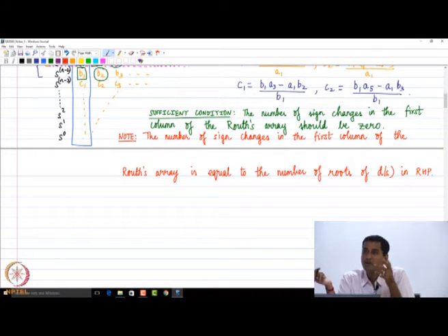How are they going to be reflected in this Routh array? Till now I only talked about positive and negative numbers, but you can always have a 0 as a first entry. If you have a 0, then we need to follow a different process, and that may imply roots on the imaginary axis. We are going to test those scenarios. I'm going to come to your question maybe tomorrow.